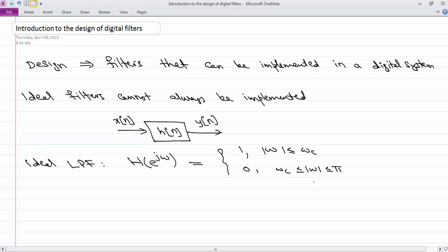By the way, let me remind you that one of the common things I see in exams is that students write 0 otherwise, and that is incorrect because a discrete time Fourier transform is not 0 after omega c. Okay, so just be careful about that. Okay, so if this is my ideal low pass filter, then you say, well, I know how to compute the inverse transform of that, and I will get this formula, sine of omega c n over pi n.